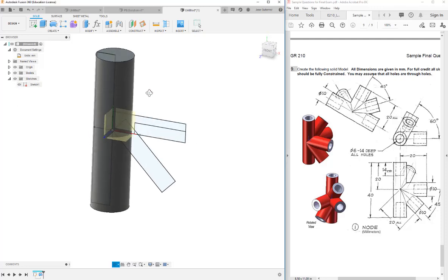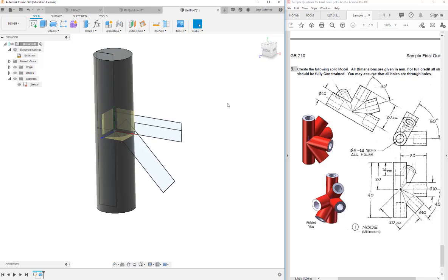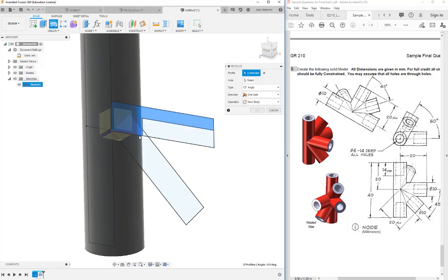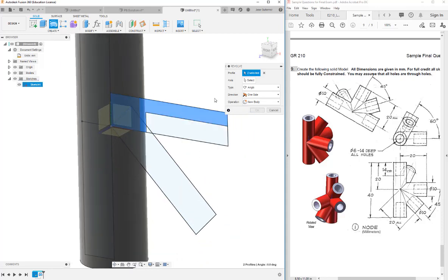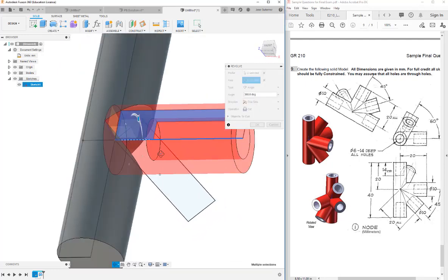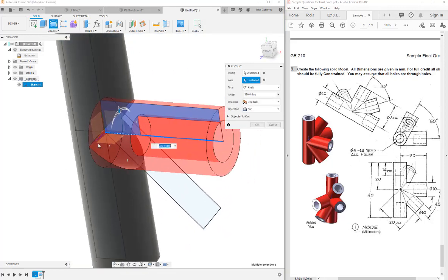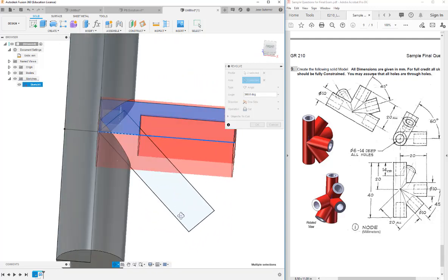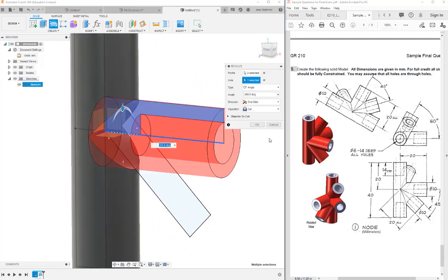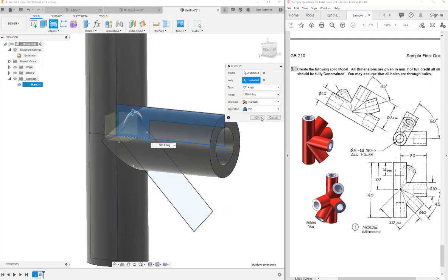Okay, I'm going to show that sketch again because I'm not done using it. So if I right click, I can repeat revolve or just go ahead and select it again. I need to select all of the parts I'd like to revolve. So I'd like to revolve that profile, and then the axis here would be my x-axis, and by default, since my revolve went through an already existing feature, it's showing that as a cut. But I'd actually like to combine them, so I'm going to change the operation to a join operation.